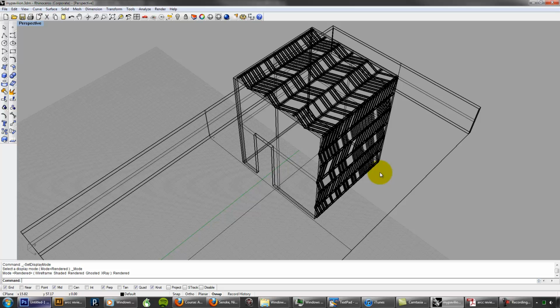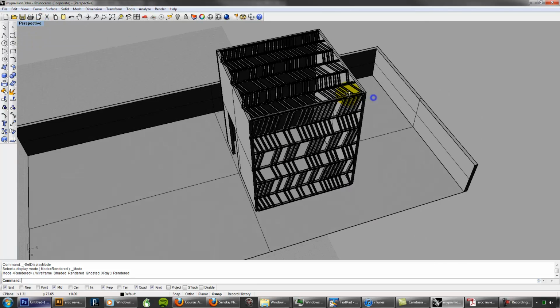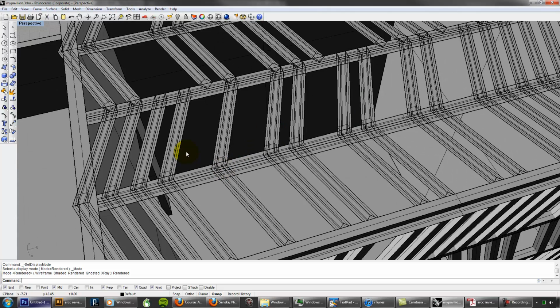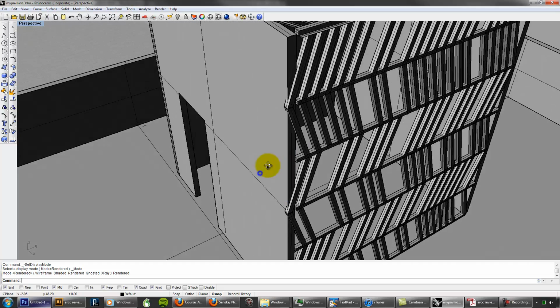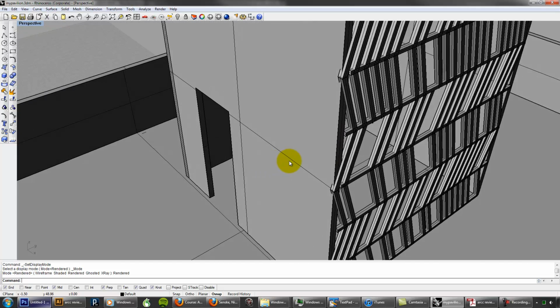This has been baked, so now it is actually Rhino geometry. You'll notice there are some craft problems with it. It overlaps here. It doesn't join this very well. You can use Rhinoceros to clean this up. I realize that in Grasshopper it's hard to do things very precisely, so feel free to make some adjustments. Don't rely upon Rhino to fix your mistakes with Grasshopper, though. It's really better to do it right the first time.